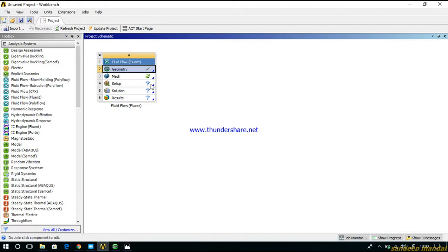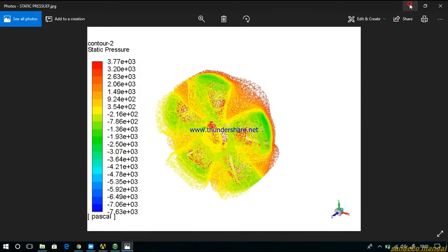And if your laptop has low RAM, approximately 4 GB or 8 GB, set the iteration value up to 20, because it takes 7 to 8 hours to calculate this kind of stuff. If you take iterations up to 100, you will need very large computational time. That's why I'm not showing you the calculation procedure. I'm showing you the direct result.